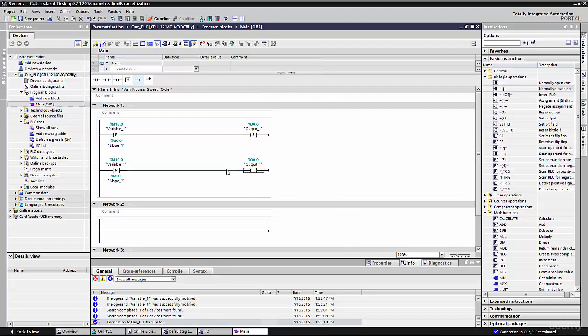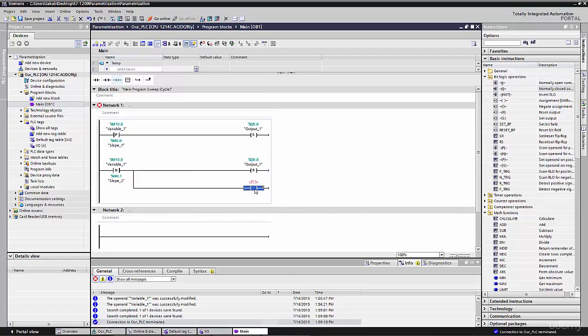So you see the main difference. I will put here this open coil. This open coil is switched on when we have a signal here, and is switched off when we do not have a signal. Next we have two other coils, set and reset, which is a coil with memory, we can say. If we put the signal here, this coil with this variable will be set permanently. In another place in the program, when we put the impulse here, this coil will be reset.